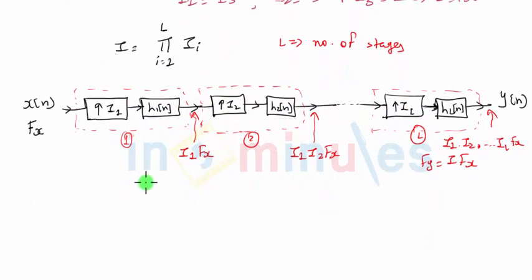So let us take decimation by a factor capital D, where D may be factored into a product of positive integers, which can be written as the product of di, where pi stands for the product. I will vary from 1 to L again. And this can be implemented as a cascade of, let me use a different notation for the number of stages just to have a general case, so let's say now we go up to J stages. So this can be implemented as a cascade of J stages of filtering and decimation.